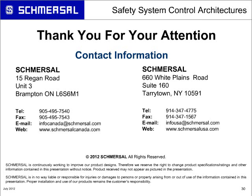So, for example, control category B is usually associated with a performance level A, or control category 1, you can achieve up to performance level A. If you need a performance level D, you're typically going to be designing in a control category 3 or control category 4, depending on where the hardware reliability comes in.